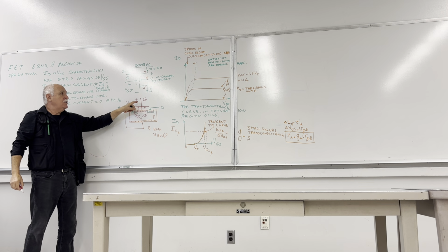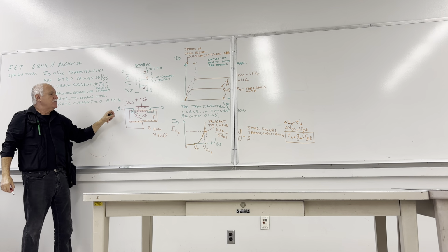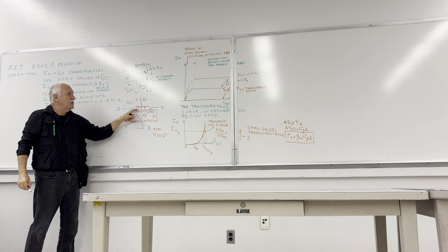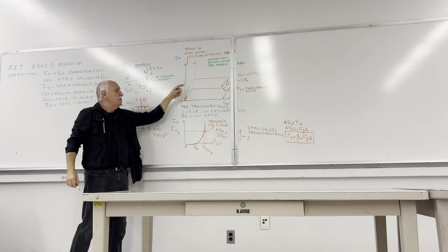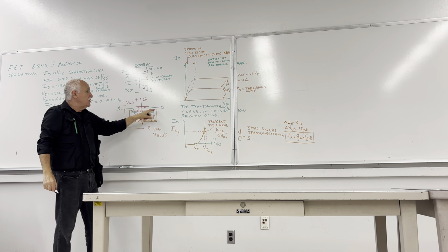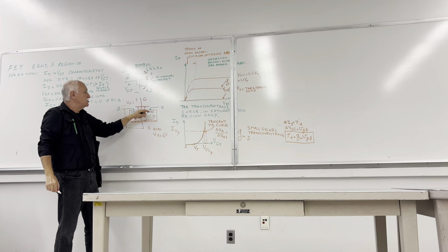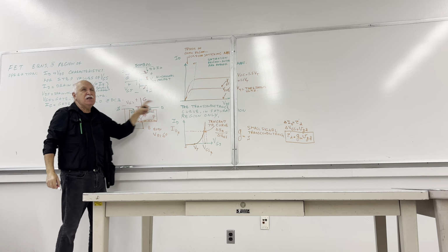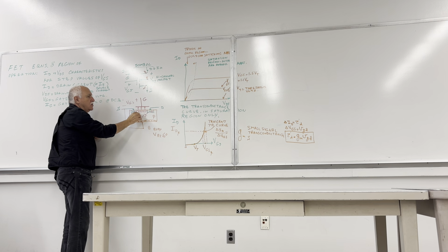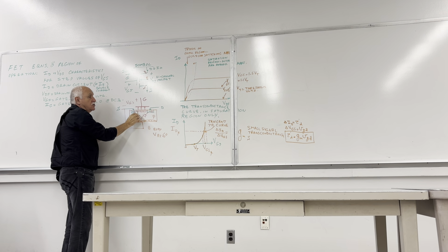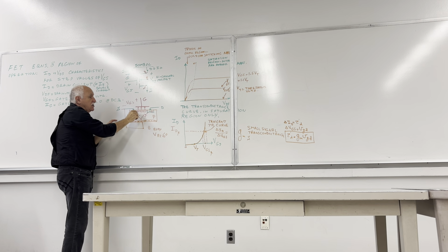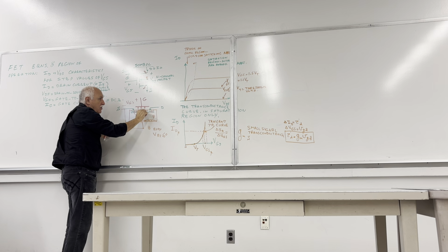So when you put a gate voltage to that, up to a certain range for small drain to source values, it will be a linear one. But as you increase drain to source voltage, given the VGS value, there is only a limited number of electrons that can exist underneath that. So the channel shape doesn't go linear, but it tapers like this.